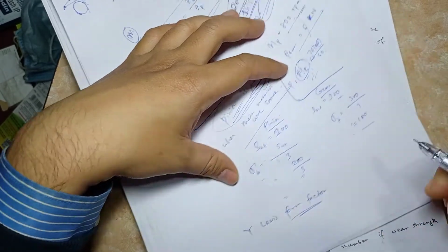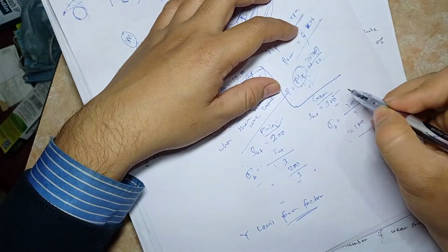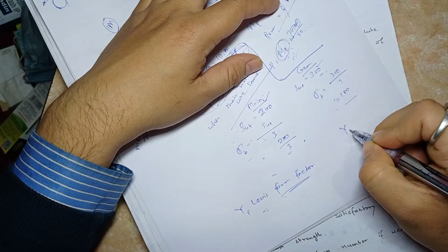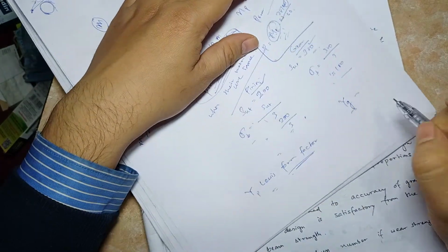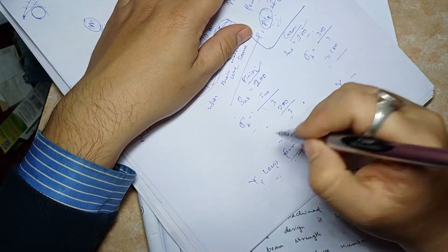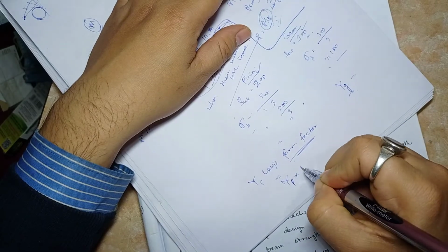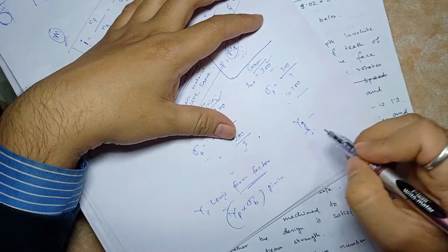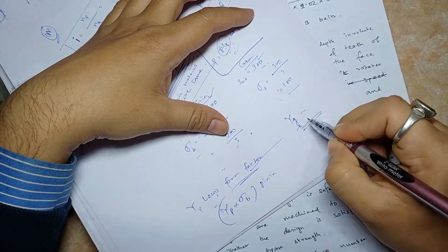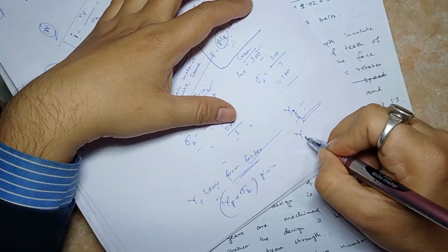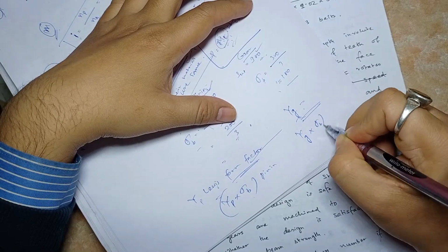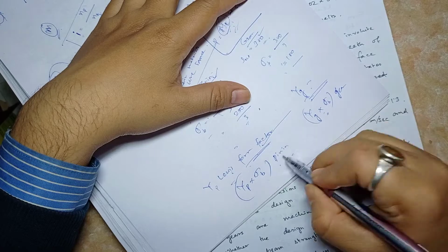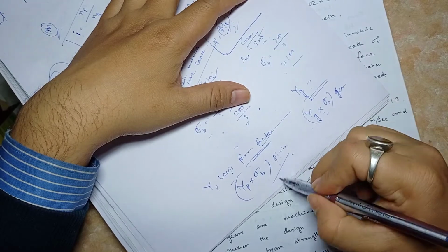And this depends upon the number of teeth in the pinion and gear. Lewis form factor for a pinion you find out, Lewis form factor for a gear you find out. I'll show you how to find out. Lewis form factor multiplied by sigma b for the pinion, you calculate after calculating Lewis form factor. Actually, this you can get from the data book, Lewis form factor, and this multiplied by sigma b for the gear. Now compare between them, whichever is lesser, that is the weaker one.